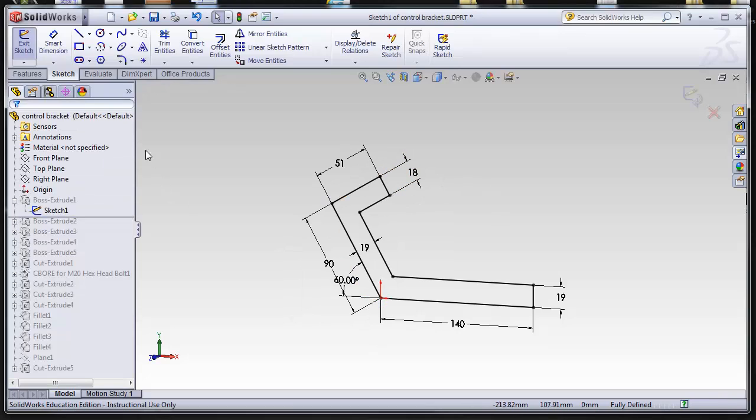To create the sketch, the line tool was used. The sketch was drawn based on the origin. Once the sketch was created, the dimensions from this point here were added, and then the values added to those dimensions to control the size of the part.